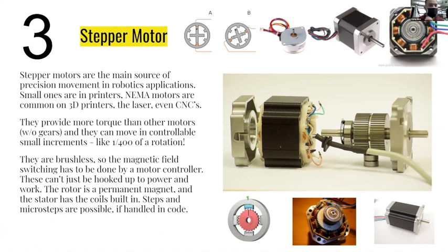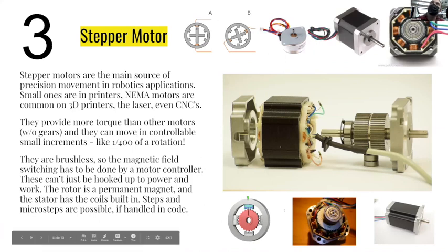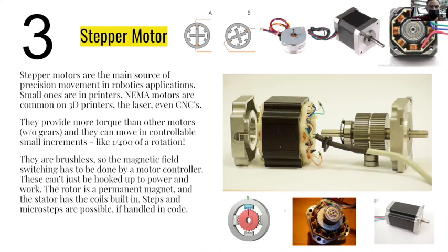You can see those like teeth on them. Those represent the steps that are on a stepper motor. These are the pieces that can move around finite amounts. Usually they're rated for a little bit more torque than the other motors. They're more complicated to drive. You usually need a stepper motor driver of some sort to make them go, but they can spin very precise amounts. So you can imagine the laser wanting to cut a line that's exactly 3 inches long. You can tell it some command and it will move to what is exactly 3 inches of motion. So that's absolutely something that's good to do.